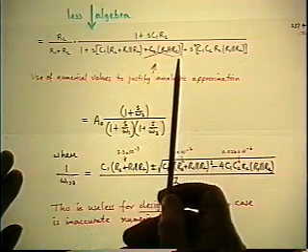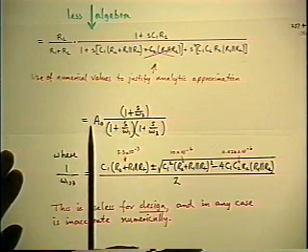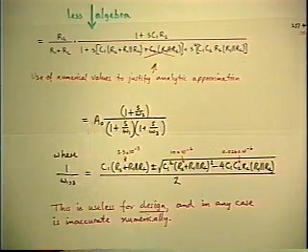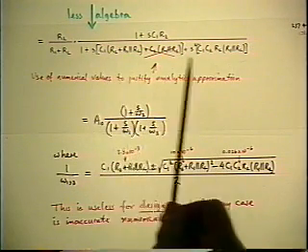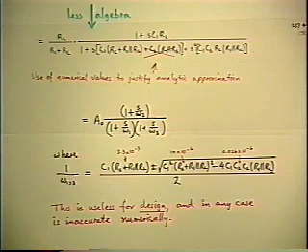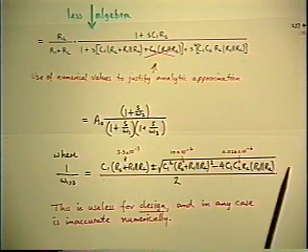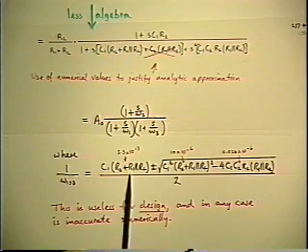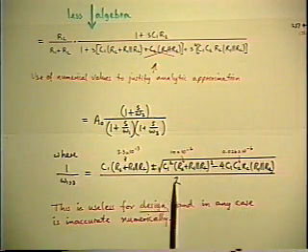All of them are in normal format, which means the coefficient in front is identified as the zero frequency flat gain asymptote. So the next thing is, what are the two poles, which of course are the solution of this quadratic equation. Even with the simplification, it remains a quadratic. And so now you wheel out your familiar formula for the solution of a quadratic. And here it is, with substitution for the ABC coefficients in terms of the circuit elements that already exist, and you can immediately see where that comes from.